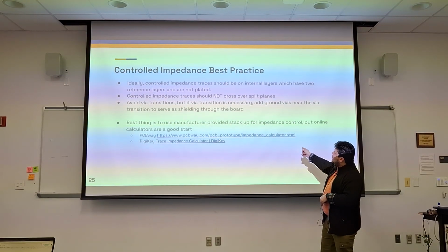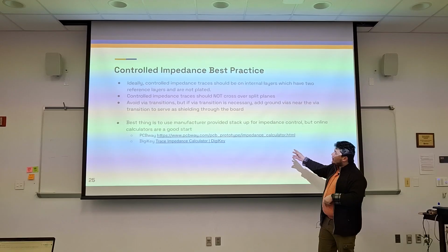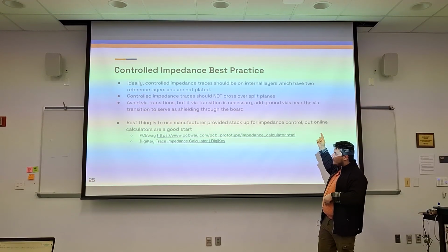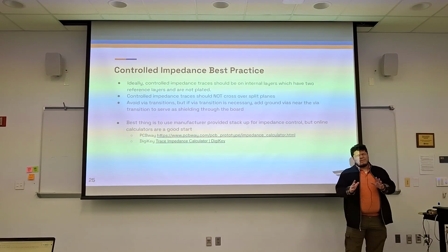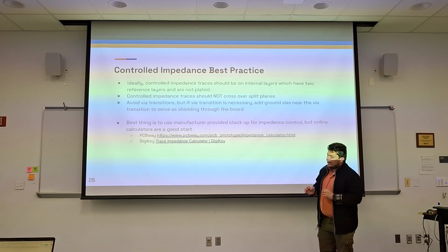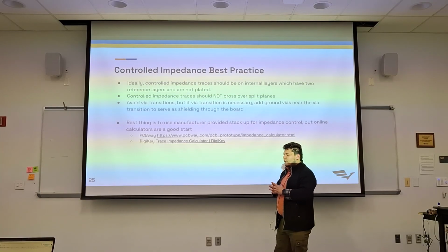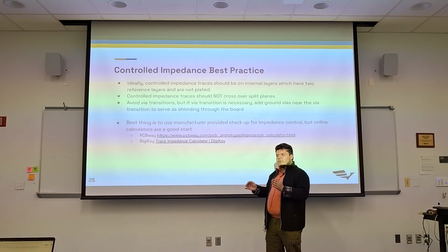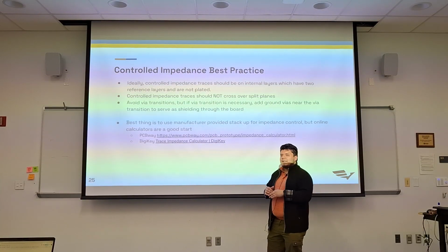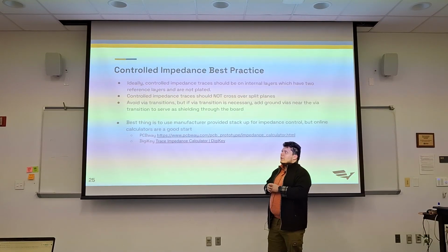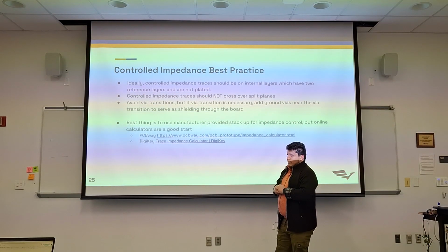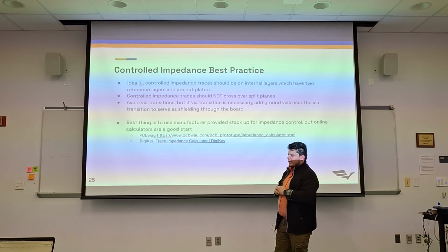But best practice, get it from your manufacturer, or you can also use a calculator. I used the PCB weight calculator for the images you saw. DigiKey also has a pretty good calculator. Little side note, technically, these calculators assume that you have no solder mask over the traces. Technically, the solder mask has a slightly different dielectric constant than air. For the most part, since we're not super high frequency, 50 kilohertz is not that bad,